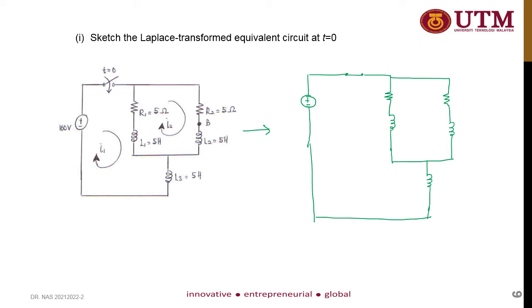Since there's no initial current or initial voltage, you don't have to consider adding the additional source in series with the inductor. So don't forget to convert all components into S domain.